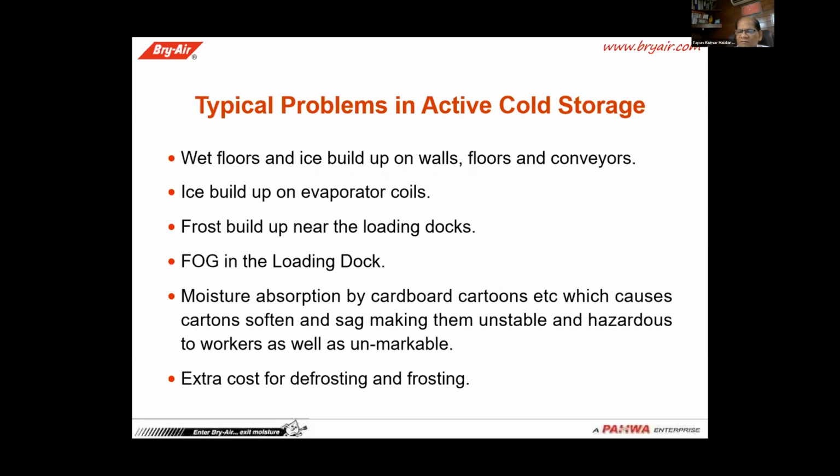Even due to this moisture, evaporator coils get choked up by the ice building. And if that happens, we have to defrost the coils, which means a lot of energy is utilized. And we cannot control the temperature properly. So the defrosting cycle is high. Then it may ultimately create problems in the product itself.